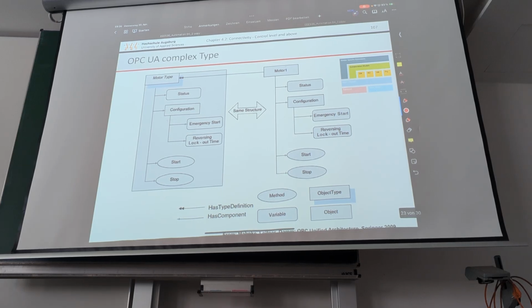But on the other hand, if you have a very simple IoT device, it's probably just too much that you have to do, and that's why you also have this simple MQTT where you just read and write data and you don't really know what the data means. It's just like, give me value 1, and then it says, well, the 1 is 100, and with OPC UA you know that this value is part of a motor, and it's actually the temperature of the motor, and it has degrees Celsius, and so on. So it just depends on how much additional information you need, whether you want this complex modeling or just simple data values.